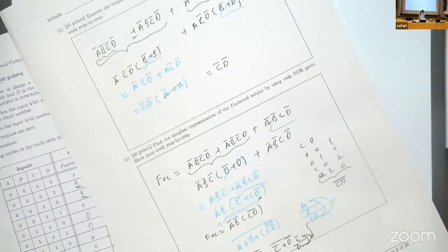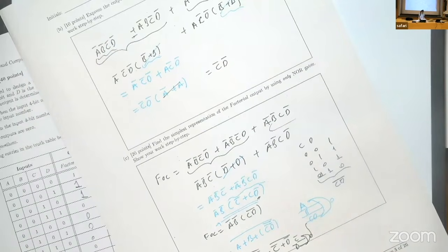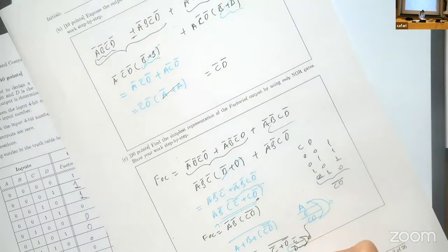And there's a simple trick for this. For any input, the negated version is equal to NORing the input with itself. So basically, if you just OR the C's and negate it, if you get the NOR of 2 C's, you get C naught. And then you will need to do the same thing for D naught. So it's also a NOR of D with itself. And instead of C, you need to have a NOR gate with 2 C's. And instead of D, you need a NOR gate of 2 D's.